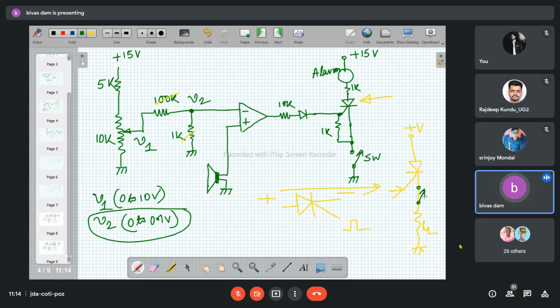So what do we normally do? We close the switch. So now the path is possible for conducting current from plus V to ground. But it is not conducting current because the SCR is still off. Now, as soon as I give one current pulse here to the gate terminal, the SCR is turned on. SCR is turned on means as if the plus V is available here itself. So there is a continuous current flowing to the RL.